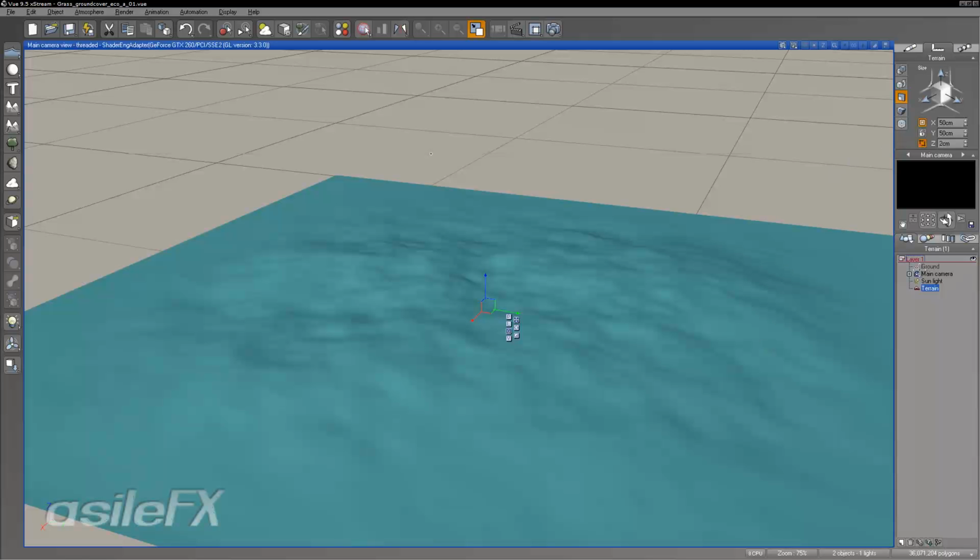Because what I'm going to end up doing is creating an ecosystem and converting it to objects, just so that after we make any changes, if we want to see them right away, even though we could just render in order to see the preview, if we decide to close out the material editor, we don't have to wait for the ecosystem to refresh.